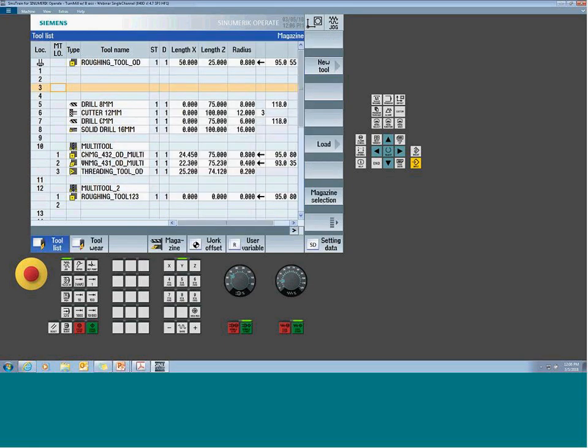And the biggest thing is the solid drill doesn't force you to put an angle value in because it's got a flat bottom. So I have a tool that's a flat bottom drill. I like to use the solid drill. It just keeps me from having to plug numbers to make a flat bottom, right?